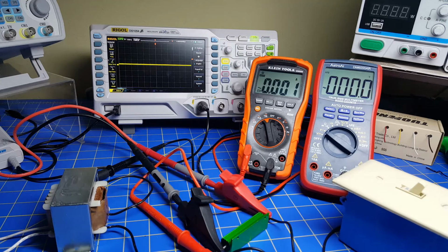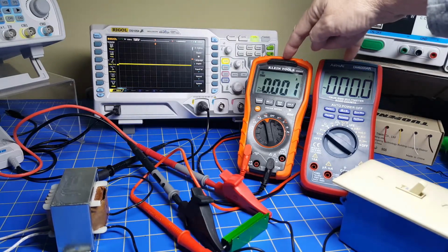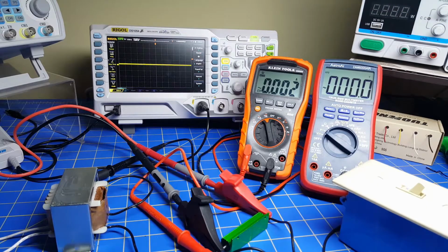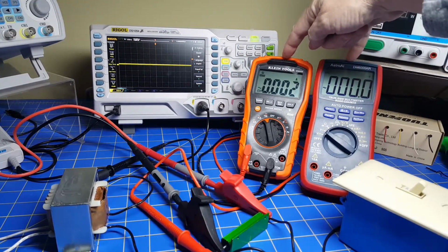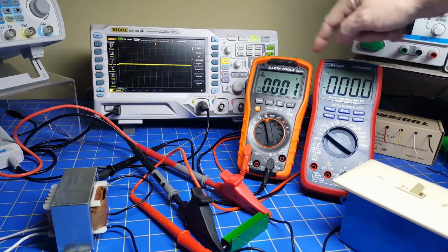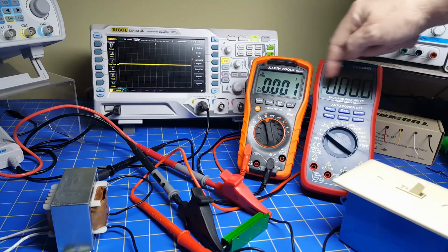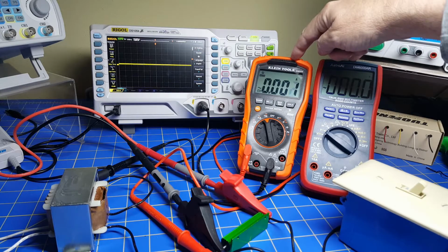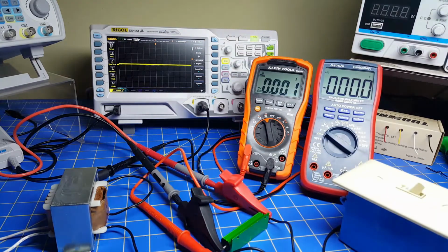Now, that being said, what we're going to do is apply from 0 to 220, say, volts across this transformer, and we're going to measure RMS current and volts. And I am going to video this so I can play it back later and see what the corresponding currents and voltages are so that we can generate our nonlinear curve. Okay, so just have to replay the video. You can do the same thing if you want. And then we're going to see on this scope the waveform, and we're going to expect it to have quite a few harmonics.